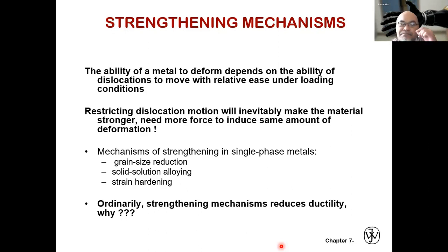So when we introduce impurity into the vacancy, it means it will be more difficult for the plane to break the bonding and then reform with the plane on the adjacent side in its vicinity. Yeah, because it is being prevented by the impurities introduced into that material. So by making an alloy, by introducing impurity, a different kind of material, maybe a smaller size element, into the gap between the planes of that crystal, then we can strengthen that metal.